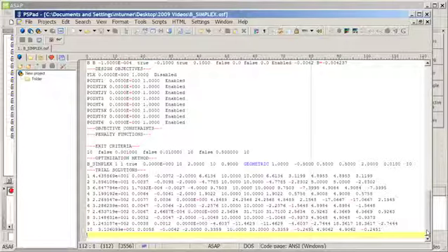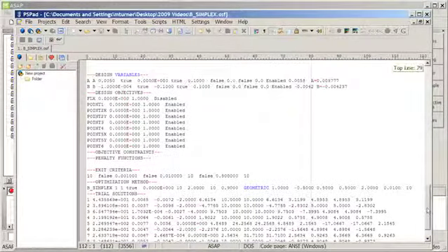You'll notice if I scroll down to the bottom of my file, I have all of my design objectives and my variables clearly indicated in a set format. And what I could do is copy and paste this data in between files, allowing me to have the code reuse capabilities that I currently have in a standard ASAP file with simply using $read commands. What this will do is if I have to perform a common optimization function many times, I don't have to regenerate the merit functions. I can simply copy and paste between files, carefully following the format defined here within a text editor, and I can do the optimization as necessary.